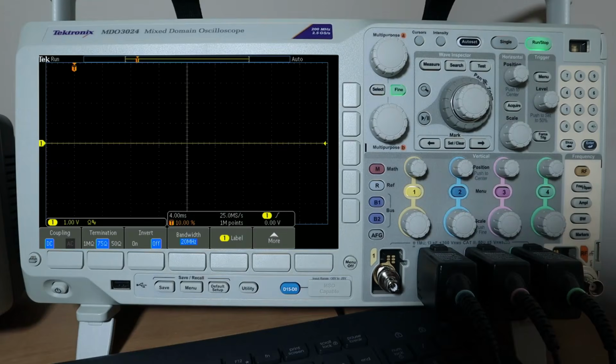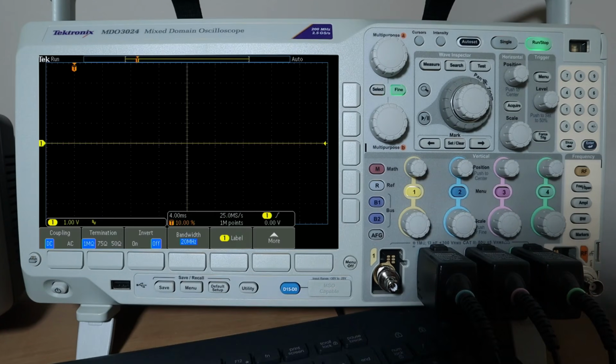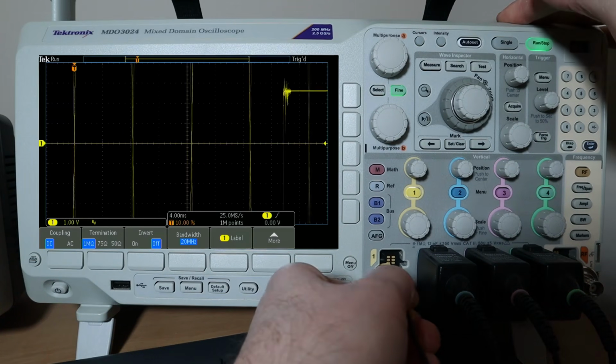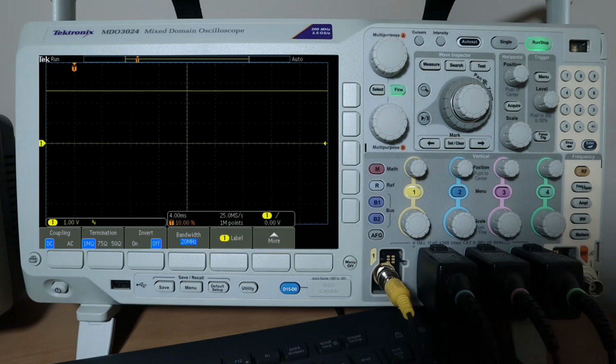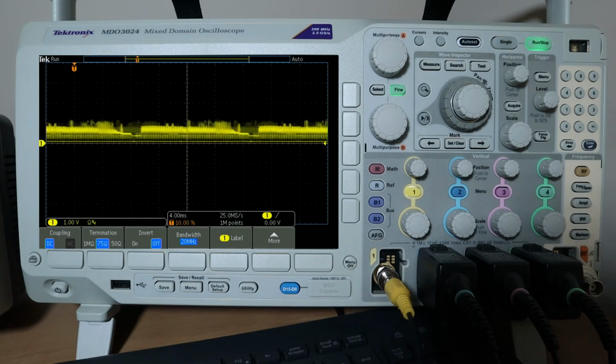so this should work out great. Now, before we get going, I'm going to set the termination impedance of the scope to be 1 megohm first, to show you what could happen if you don't use 75 ohms. The Blu-ray player is on, so let's plug it in. In this case, the signal looks like a straight-up DC voltage, around 2.6 volts or so. Now, let's switch to 75 ohms. That looks a little better.